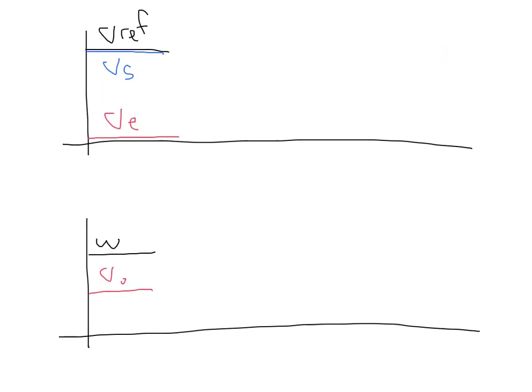in this control loop. So here we have our reference voltage up top and our speed voltage Vs. And you can see that in steady state, we've just reached some steady state. These two quantities are equal to each other. If those are equal to each other, we have zero error voltage, so our error is 0. And at this operating point we have some omega or some motor speed, and to get that motor speed we're sitting at some VO, some control input to our motor driver.